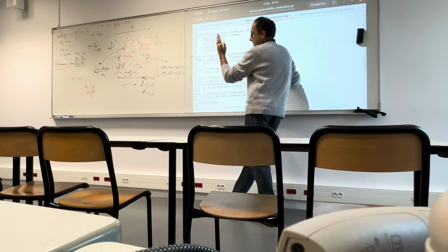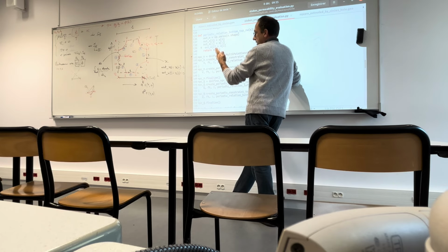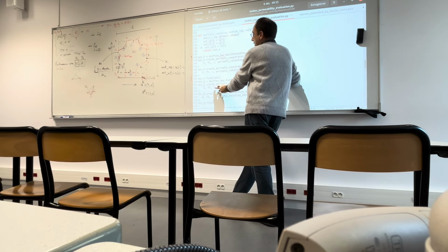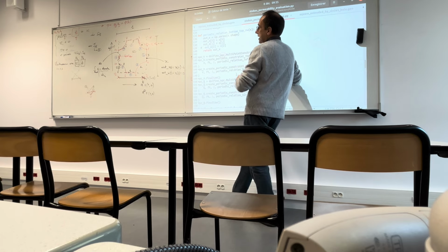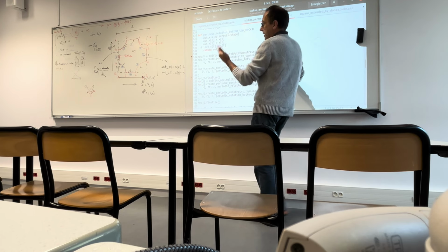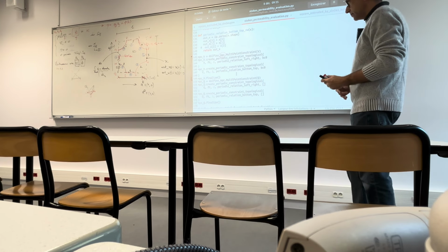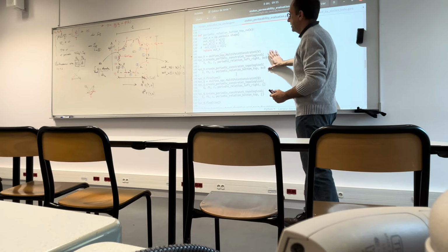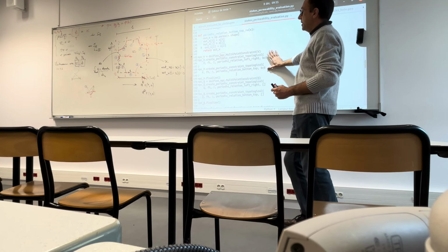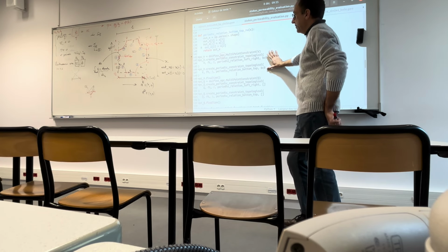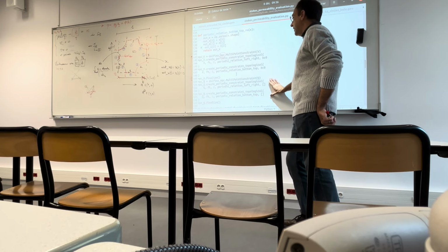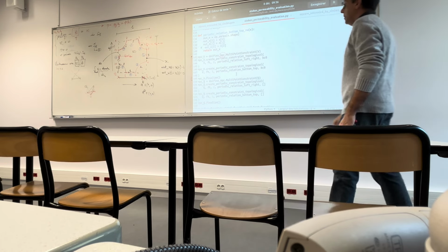So once again, master points are those on the part of the boundary labeled as 2 and 3, and the corresponding slaves are 1 and 4. So this part finalizes periodic boundary condition assignment for velocity, and this part for pressure.